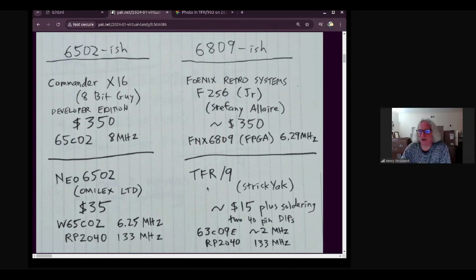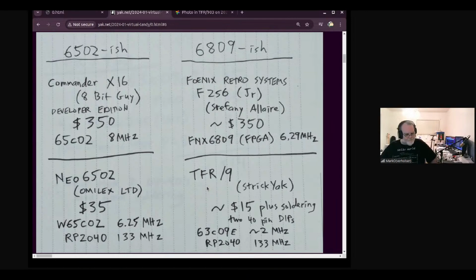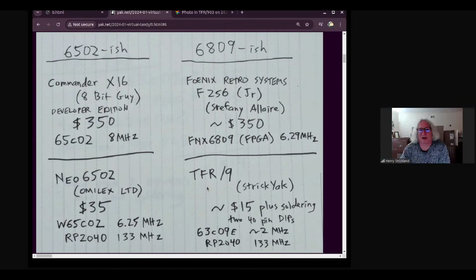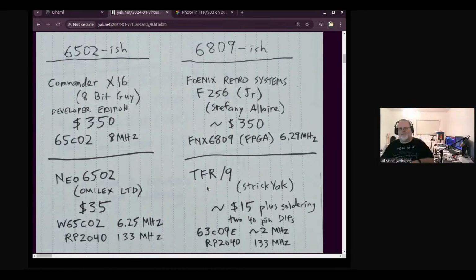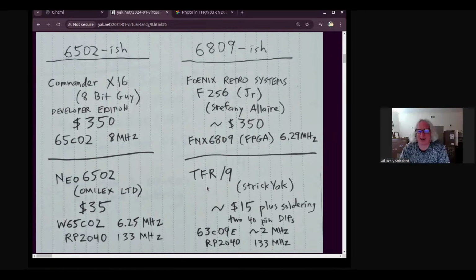Okay. But the deal is that the clocks are not coming out of a crystal. The clocks are coming out of code in the RP in the Pico. And sometimes that code has more work to do than other times, like if it's doing a disk access, and then I go and send a lot of data around and the clock quits running.